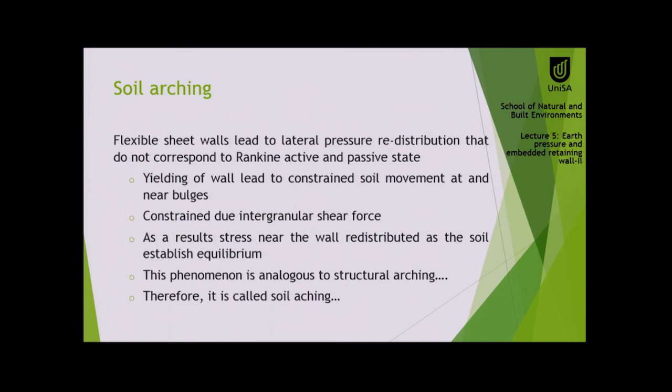So that is the solution. Okay. We still need some time to explain some of the concept. Of course, as I started this lecture by saying, everything we do over here is in terms of Rankine earth pressure theory. Rankine earth pressure considers the possible failure state, the failure stress of soil. So the pressure diagram we draw does not necessarily develop in the soil. It could be different. But if Rankine pressure is the theory, before failing the soil, that pressure would develop. So that satisfies the design criteria. If we design based on Rankine theory, it will be safe.